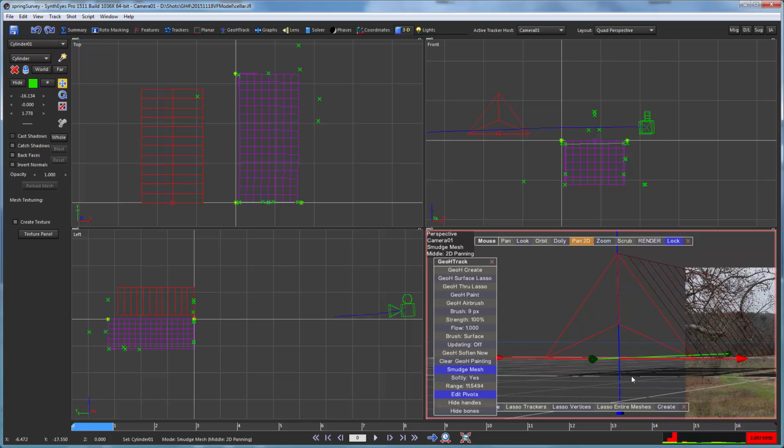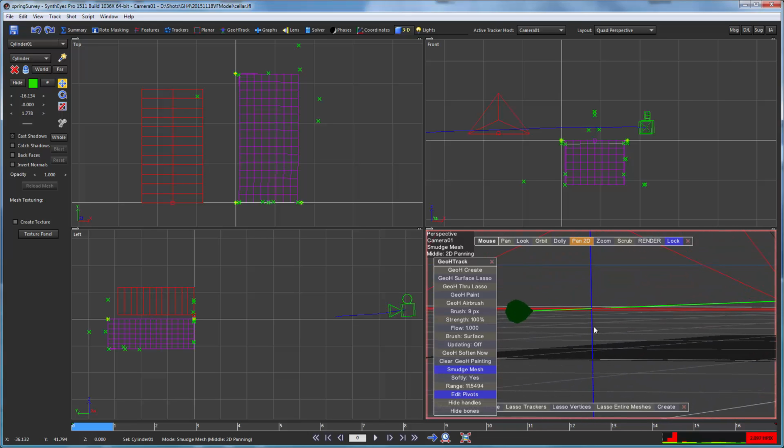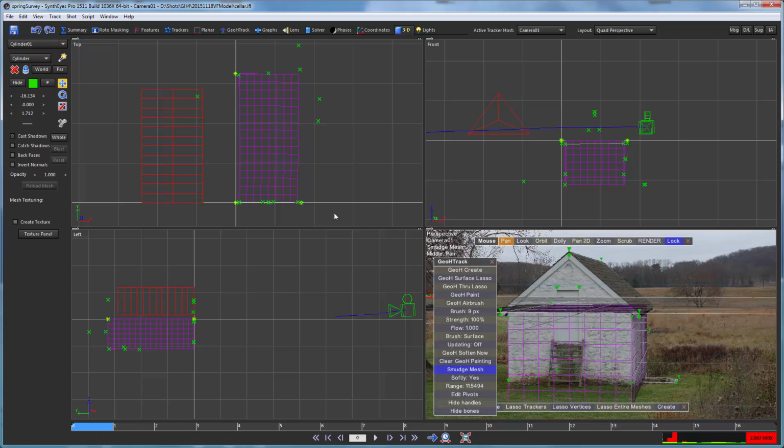And I'll point out that there's a snap to the pivot position that lets it get exactly to the edge of the bounding box of an object. But you do have to zoom in a little, so that it gets close enough to the edge that it'll snap onto it. So that's why I zoomed in there a bit. Let's turn the edit pivots back off.